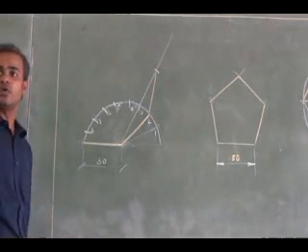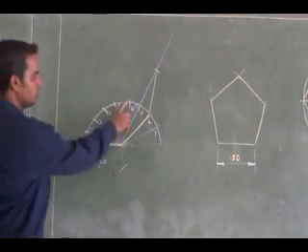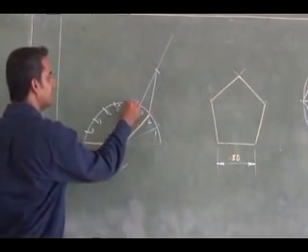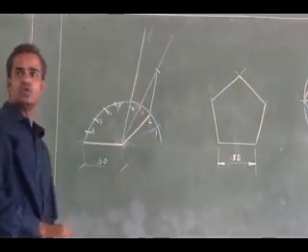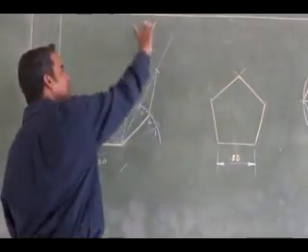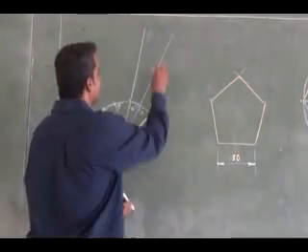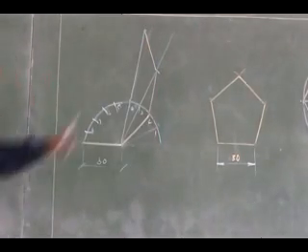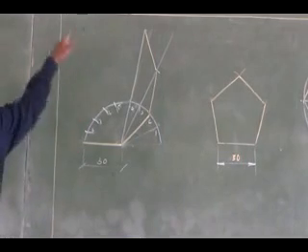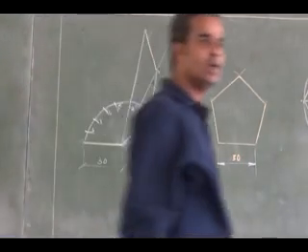Going to the fourth side, I can draw a construction line through the fourth division. From third to fourth, the same 30 mm I can cut here. So I will end up like this. In the same fashion, if I finish it, I will get a regular polygon.